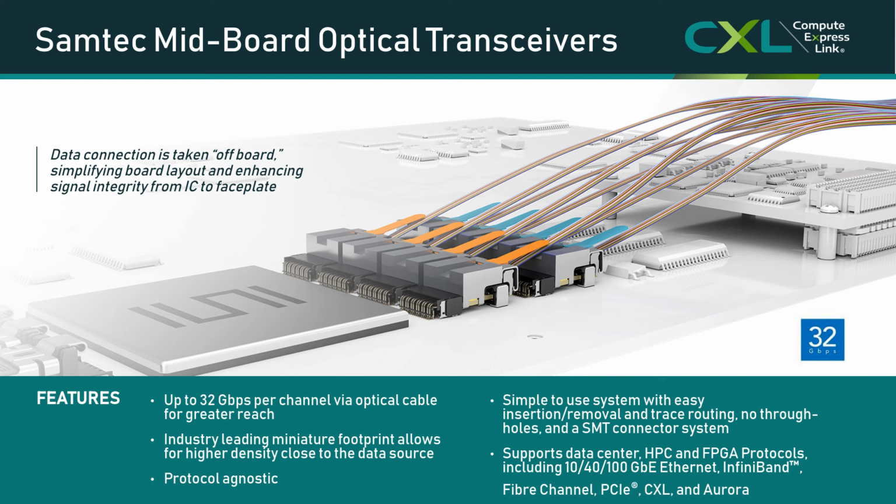How do we do that? Well, Samtec, without going into all the product details, just want to hit a few of the highlights. Samtec has a growing family of midboard optical transceivers, and the illustration here shows that by placing the optical transceiver directly next to the ASIC in the system, GPU, FPGA, memory controller, whatever the case may be, you simplify the PCB layout, the signal trace from the ASIC directly to the optical transceiver. In the electrical domain, you're literally going from the ASIC pad through the PCB to the onboard PCB connector, and then entering the optical engine within that small PCB form factor.